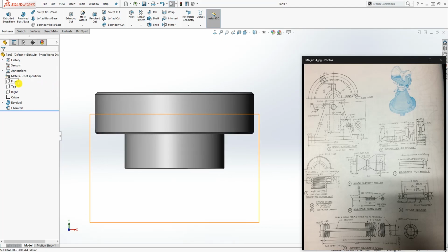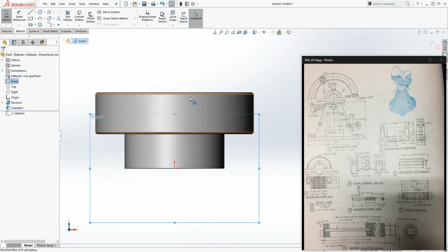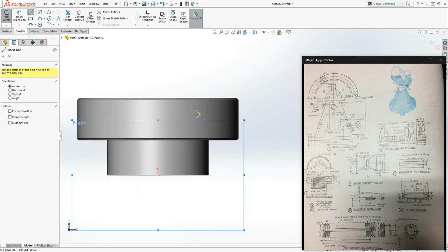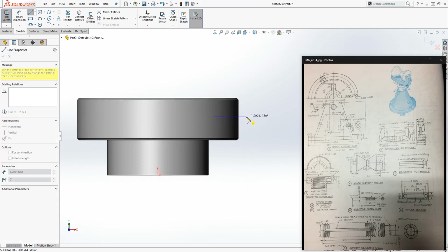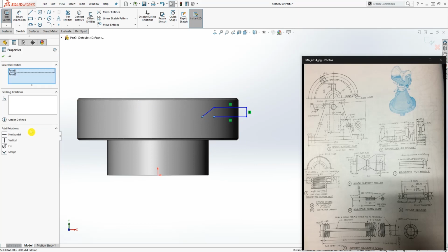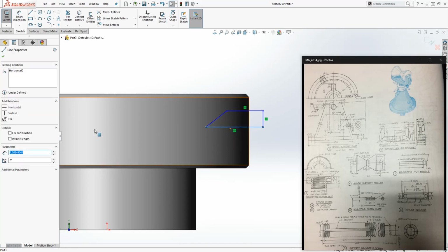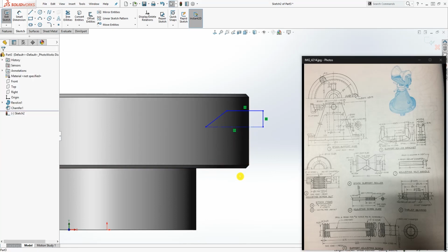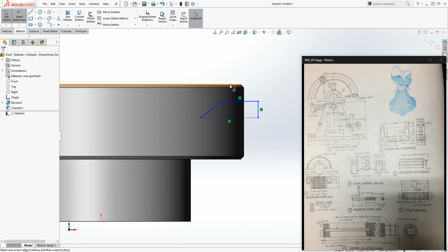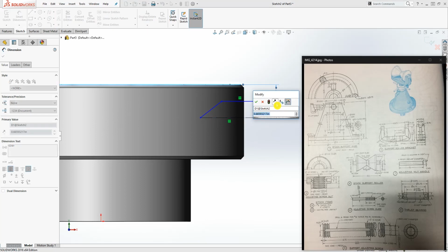And on the front plane, sketch, just draw something like this for now. You can use a rectangle too. A rectangle will work. Something like this. So something that looks like a match these 2 points. Okay, so now make this a construction line, and from the top edge to this point is going to be 0.75,